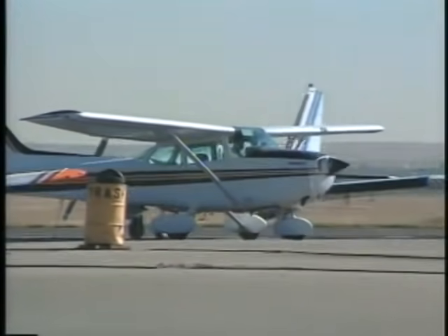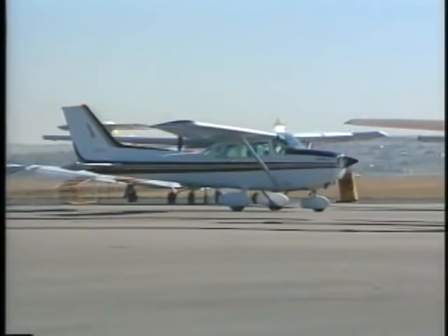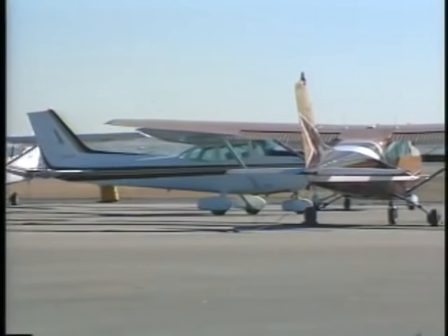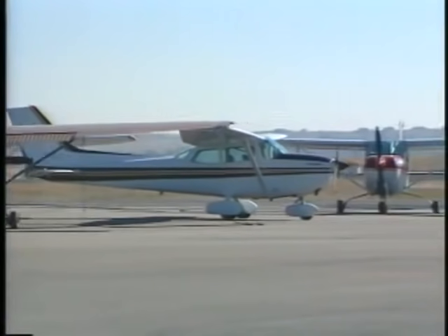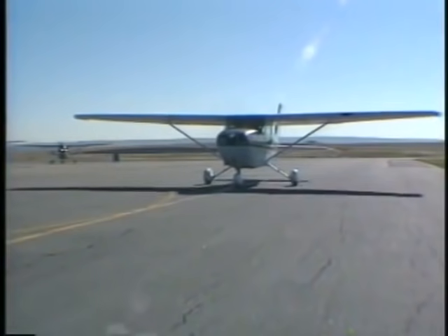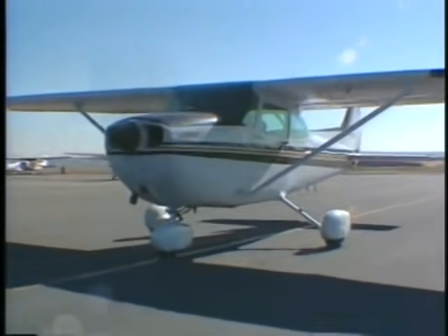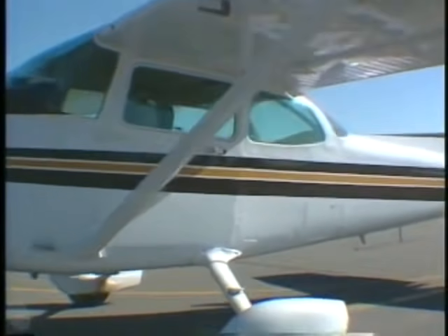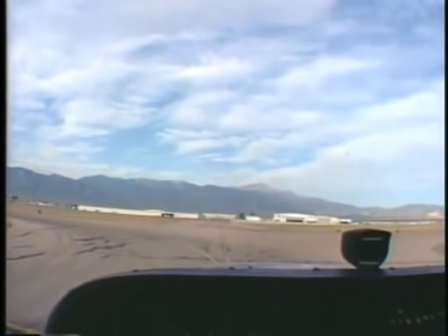Complete as many checklist items as possible before taxiing. Concentrate on your primary responsibilities. Do not become absorbed in other tasks or conversation while the aircraft is moving. Read back all clearances involving active runway crossing, hold short, and taxi into position and hold instructions. If you are unsure of your position, stop and ask for assistance.